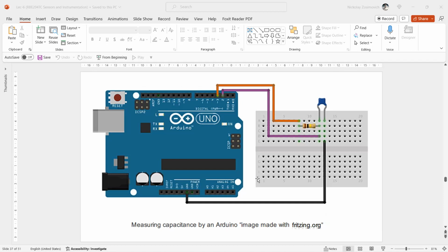The described method uses the microcontroller input and output pins to charge, discharge, and detect the voltage level of a capacitor. Instead of sensing a change in capacitance, the voltage used to charge the capacitor can be measured using this strategy. With fixed values for the capacitor and resistor, so a fixed value of RC, the charge time will be determined by the input voltage.